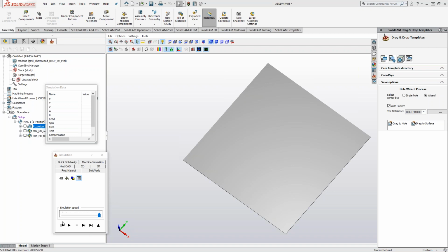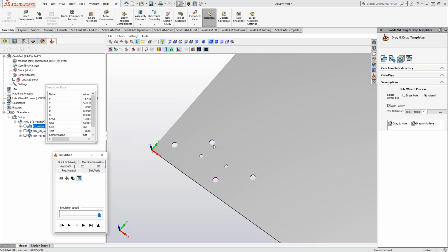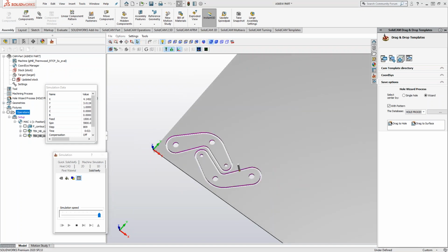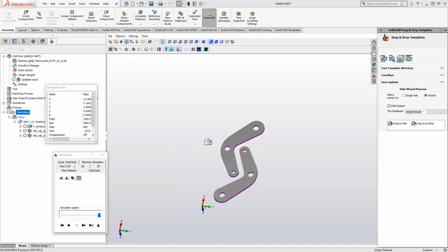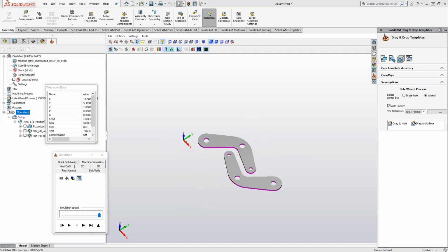In the case of the profile, it actually is removing little bits there. So that's why those little slugs are popping out. If I did the entire part, what happens is it leaves behind the target, which in reality is probably what you're looking to do. Because then once you do side 2 or another machine setup or something like that, that's probably what you want to retain going forward.